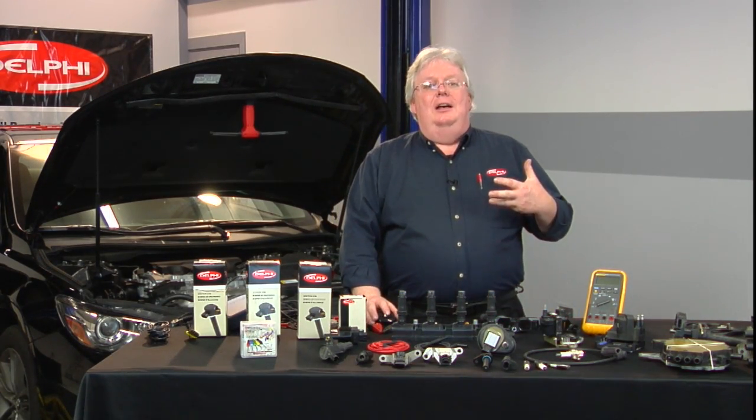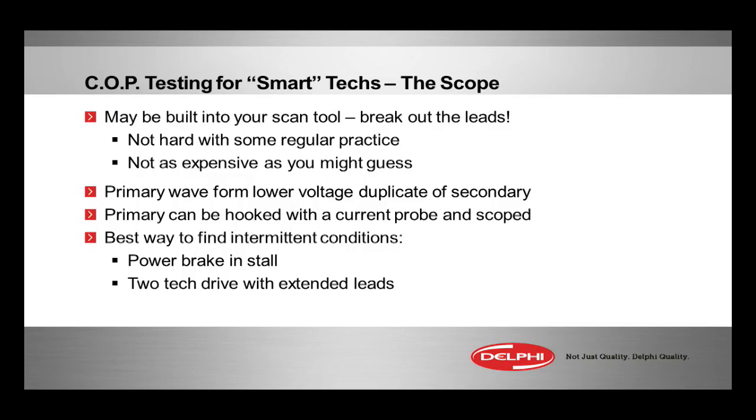Now, looking at the scope issue, if you don't have a scope, get one. I'm going to encourage you. We get more into patterns here, but the bottom line is start going at it. It really is not going to get better when it comes to technology. You're going to need a digital storage oscilloscope no matter what you're working on, if you're working on intermittent mass airflows or data buses or direct ignition or direct injection. It all boils down to good equipment.